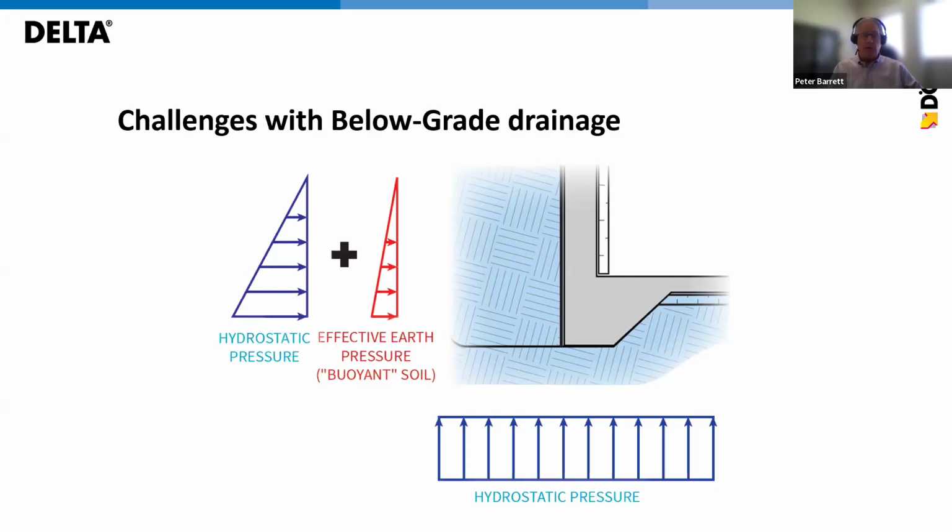So that means that your foundation has hydrostatic pressure on it, as well as the effect of earth pressure. You can simply define hydrostatic pressure as resting water exerting a load on an adjacent solid entity like a concrete foundation wall. The consequences of hydrostatic pressure on unprotected below grade walls can lead to structural damage, mold, and pests such as carpenter ants or termites. All of that can happen.